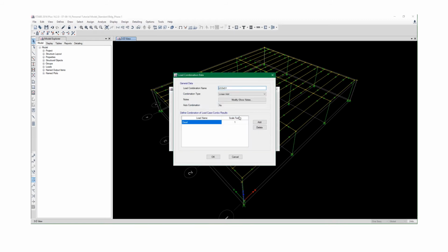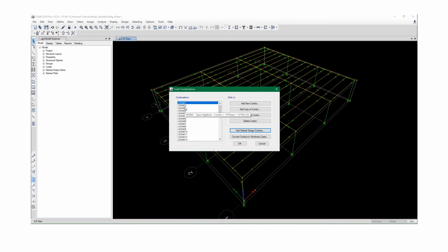You can go into it and see what each one of these combinations is. You can hover over it and you get a quick preview of what it is too. Dead load with the notional load in the X direction, and you can see the first portions of these are essentially gravity loads with notional loads combined with them. Then you finally would get into your lateral load. Looks like about 16 to 17. You kind of get into your lateral load, 17, 18 for wind load cases, and the permutations for the different combinations. Then later on, of course, earthquake, same thing.